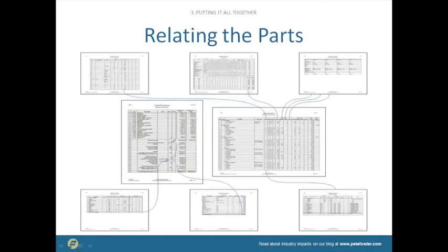And here it goes. There's a project cover sheet, or excuse me, this is not the cover sheet, this is the summary sheet. On top of all this, we will put a cover sheet that says what the estimate is and who did it and when it was done. But the summary sheet pulls everything together, as you can see from all these little lines. The two primary sheets are this estimate summary, which is either 1 or 2 pages long typically. It shouldn't be more than 3 pages long, even if it's a billion-dollar project. You should try really hard to keep it to 1 or 2.